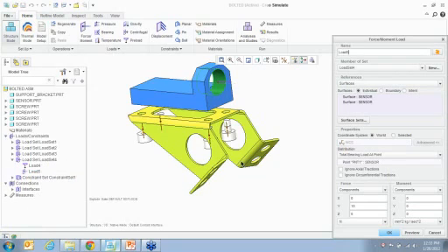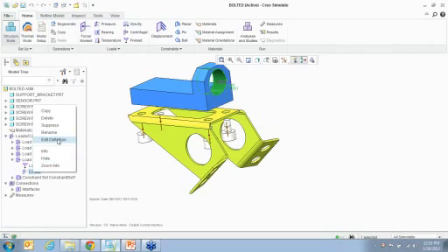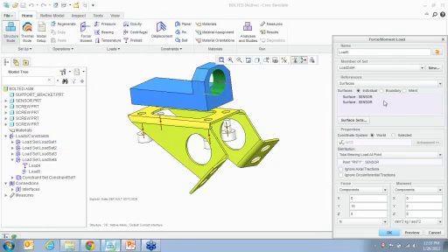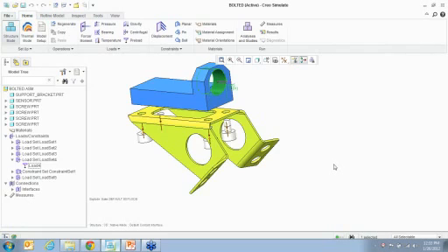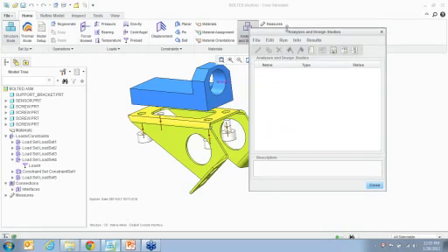But if I want to know what happens if I go step by step, if I tighten bolt 1 and then bolt 2 and then bolt 3, 4 and then apply the load, what will happen? You can set that up because you have this new enhancement within the analysis box.